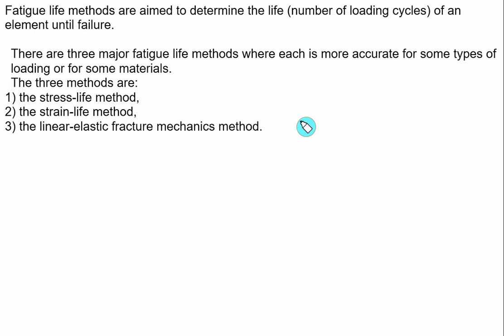While some machine parts may see only static loads in their lifetime, most will see loads and stresses that vary in time, and the material will behave very differently in response to the loads that come and go, which is called fatigue load, than it does to loads that remain static. Most of the machine design deals with the design of parts for time varying loads, so we need to know the fatigue strength of the materials under these conditions.